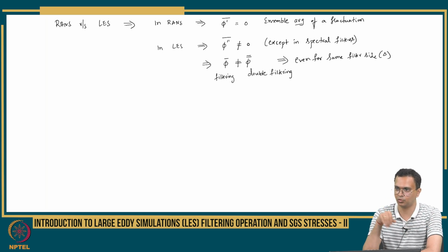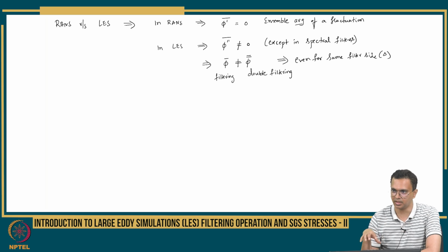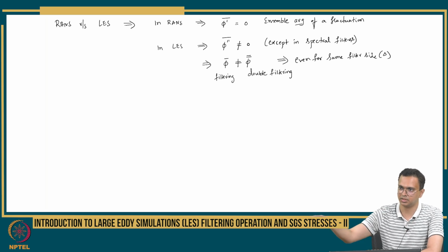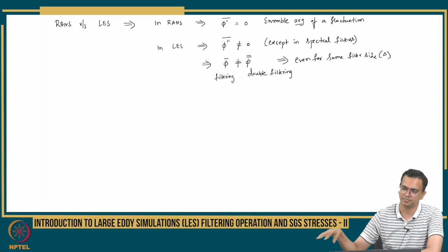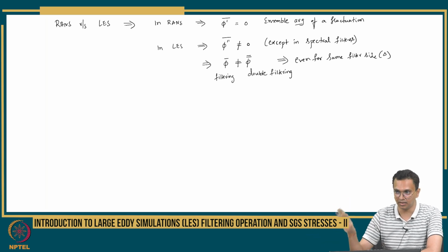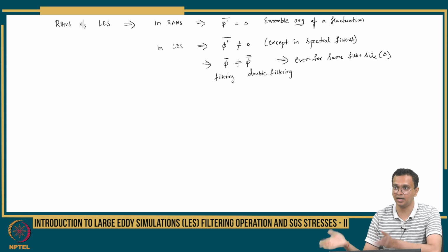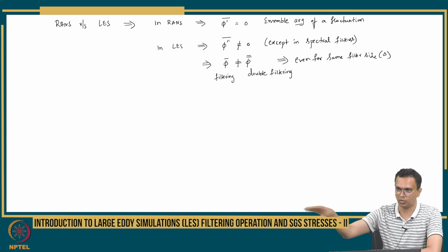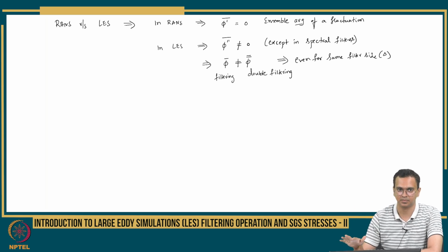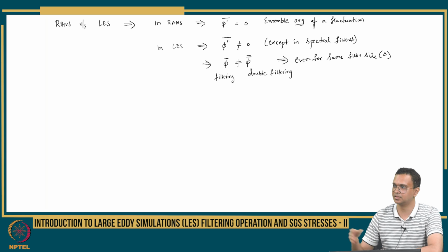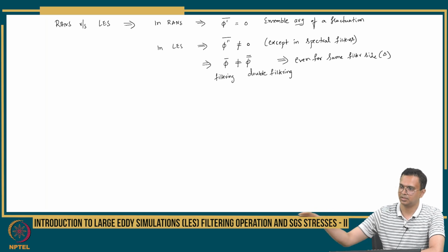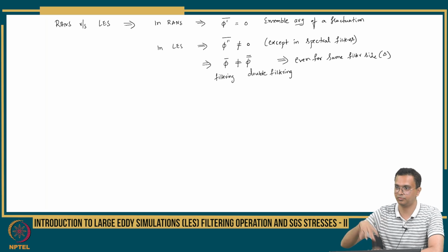You are going to make it into 4 squares, and all the thermocouples in that big square you are going to average. So some information is lost there, right? But here you are assuming that you have 10 by 10 thermocouple data and you are doing some averaging over a volume. But what if you are asked to compute only for this 2 by 2 temperature? Obviously it will not be the same as averaging the data from the 10 by 10 filtered to 2 by 2.